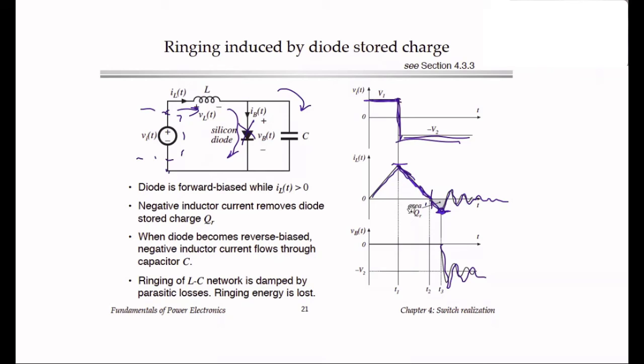The diode induces energy storage in the inductor, which is then lost after the diode turns off. However much energy loss that is, let's call it W_off. It is the energy lost in the diode turn-off transition. That energy multiplied by the switching frequency is another form of switching loss. And so in our power converters, when we see ringing like this that decays, that ringing is an additional component of switching loss.